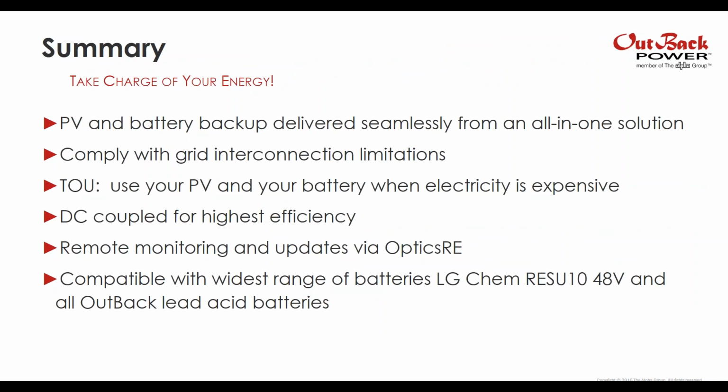It has PV and battery backup delivered seamlessly from one all-in-one solution. It complies with all grid interconnection limitations. It supports time of use, so that allows you to use your PV and your battery when electricity is expensive. SkyBox is DC coupled, so that is a direct DC link from PV down into the battery.